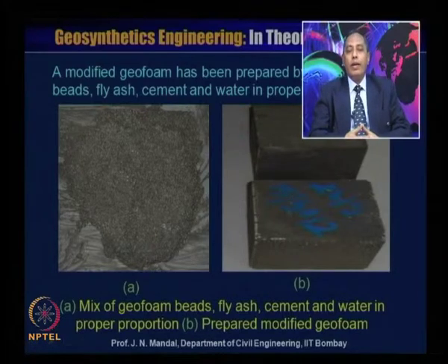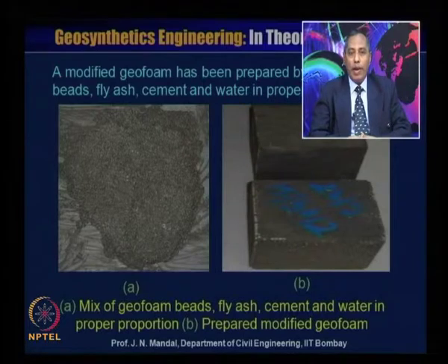Because we are using waste material here, that means fly ash. And if we find that geofoam material or expanded polystyrene material is expensive, then as an alternative to that geofoam material, you can make use of the new generation geo material, which is also very light and can also provide a very good compression effect. I will later focus on this related material.